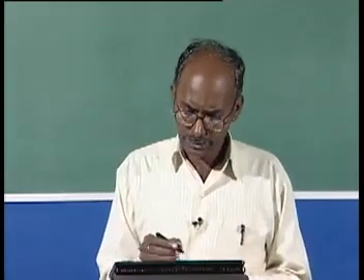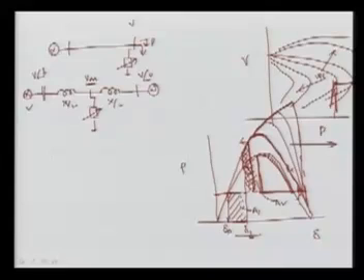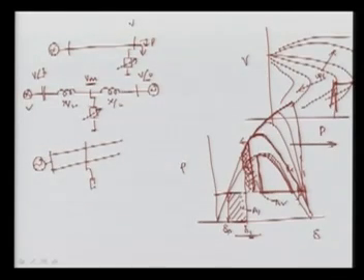So similarly we can also explain, let's suppose our system here is a generator which is feeding and connected with the two lines. Let's suppose we are putting a compensator here and here is the infinite bus, and again we can now show for the other conditions, another system. Here it was a single line, now we are having two lines and a fault occurs here. We can show again the transient stability limit will be improved significantly.